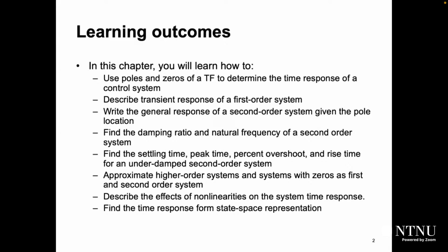We need to know how to approximate higher order systems and the systems with zeros as first and second order systems. This is very, very important because most of the design techniques are developed for second order systems. So it's very important to know how to approximate higher order systems as a second order system.